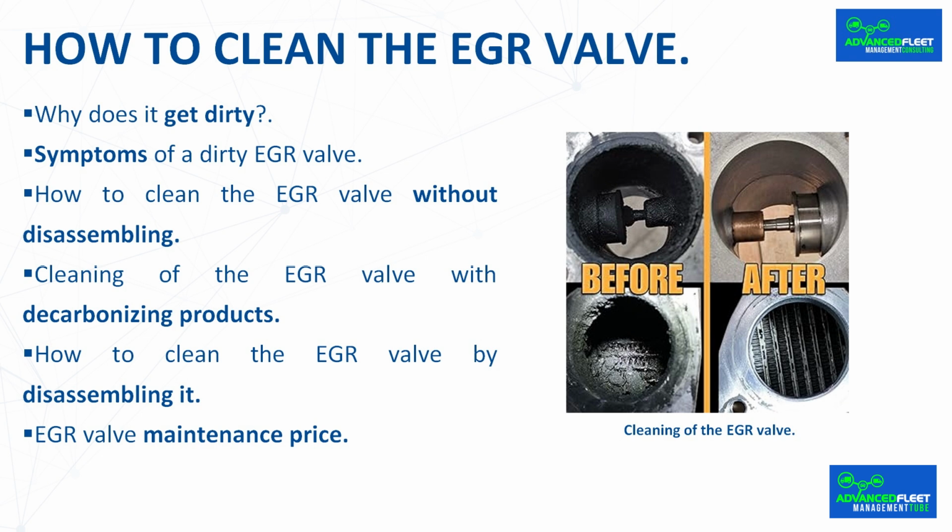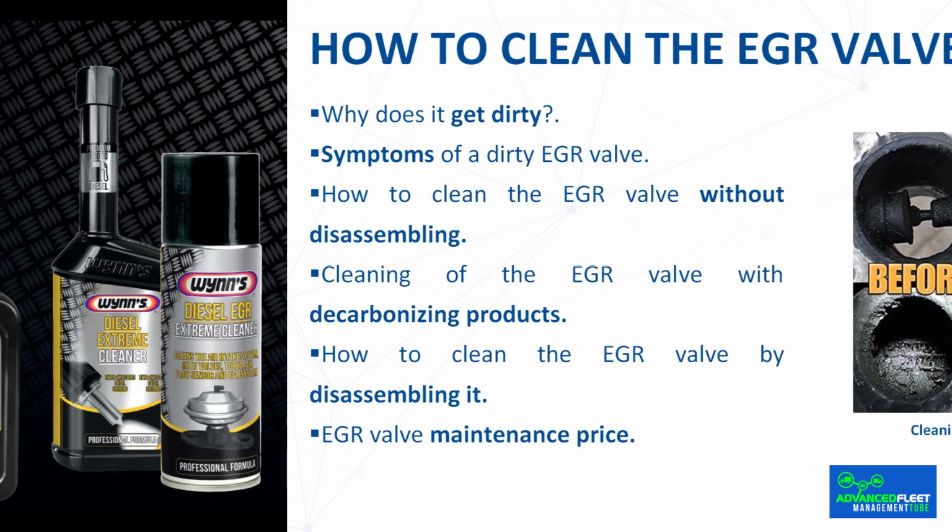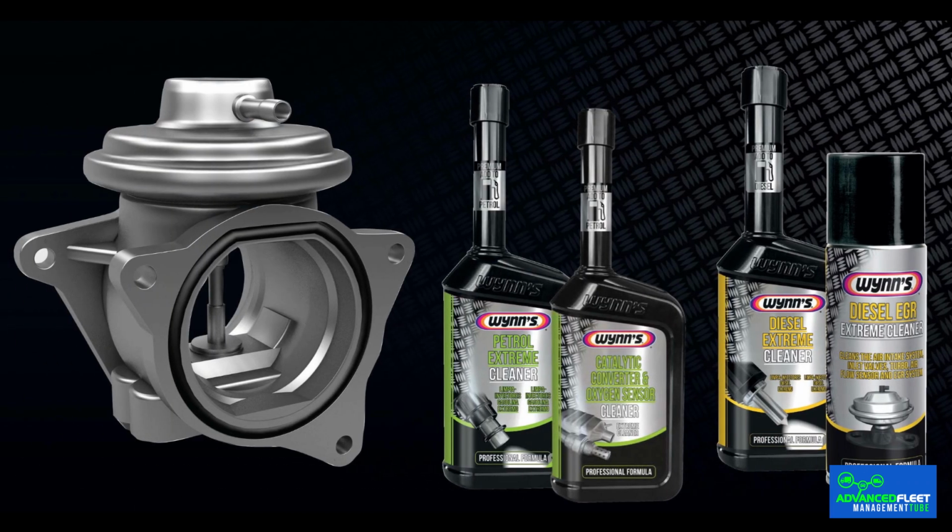Heavy acceleration in high gears. This technique can help clear minor blockages by forcing increased gas flow through the valve. Fuel additive. Using specific engine cleaning additives can help dissolve debris within the EGR system and other engine components.